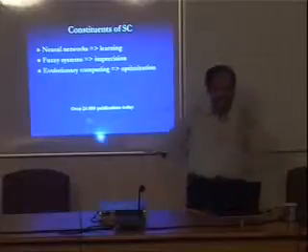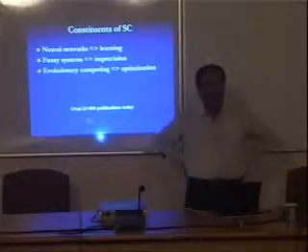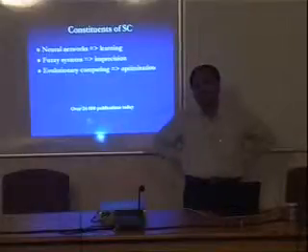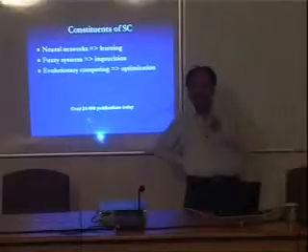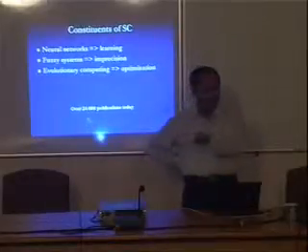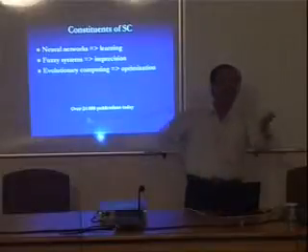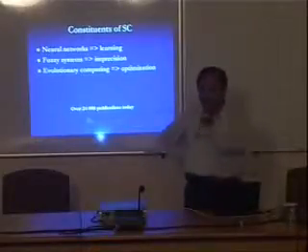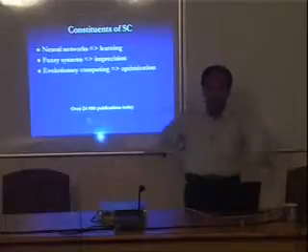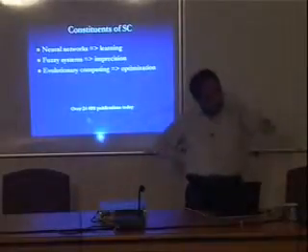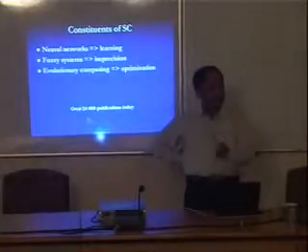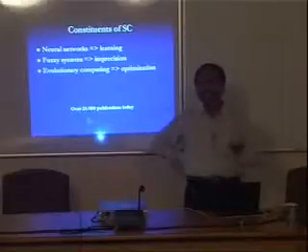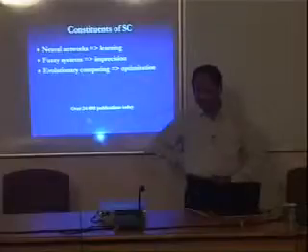This is indirectly hinting at the noise phenomenon in engineering practice. Inputs are there, but the input was 4 volt earlier during training, and that 4 has changed to now 4.1 or 4.2. A little bit of change is there. It is not that from 4 it is going to 0. 4 going to 0 is the transducer failing, but 4 changing to 4.1 is some error somewhere that has been introduced, which is nothing but noise in the measurement.